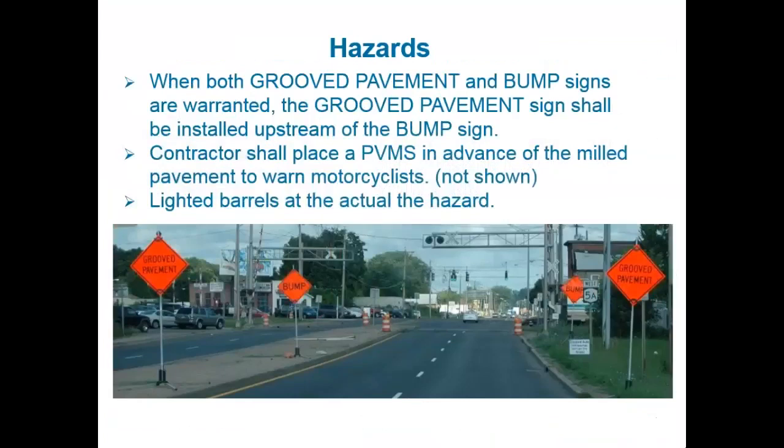Some other hazards. Groove pavement. This slide looks familiar. That's us. Groove pavement and bump signs are warranted. Groove pavement sign comes first, and then the bump sign. Okay? And then you can see we don't have a VMS there, but we do have the barrels actually at the bump with the lights.